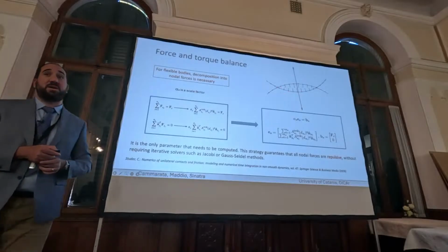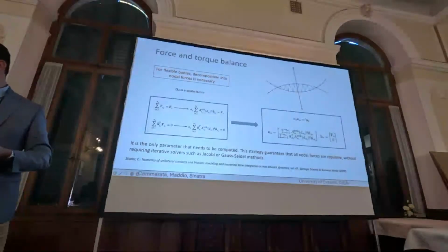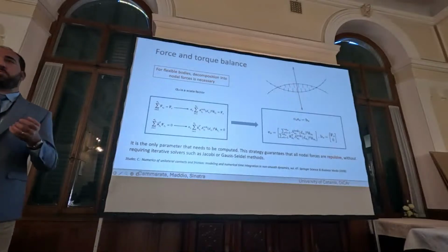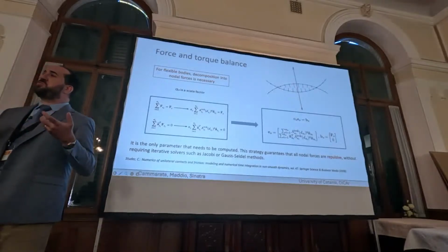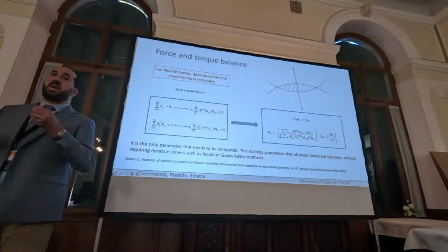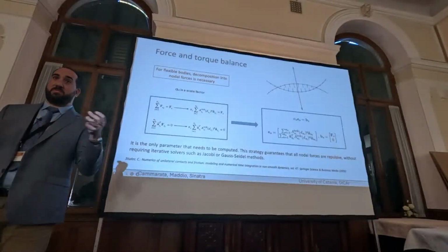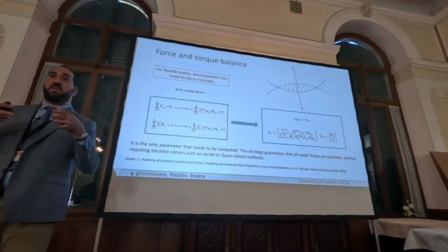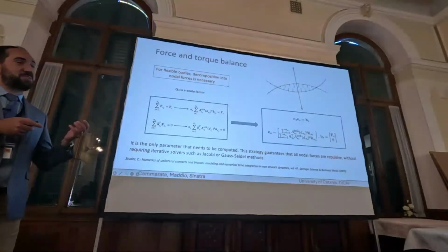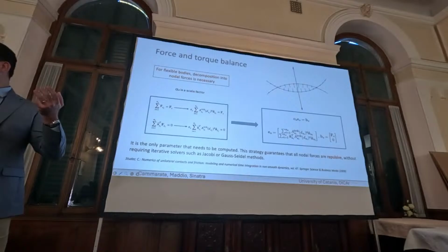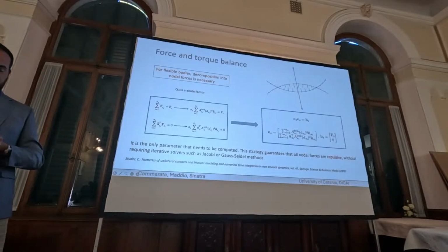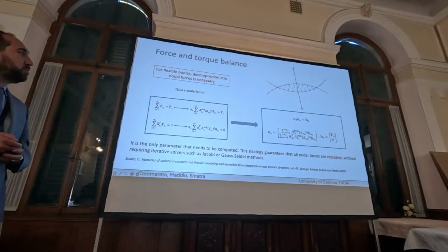But if we are interested in modeling flexible bodies, we have to perform an inverse process, because usually, for example, if you use the FEM, you start from the element, and then you assemble each element, which gives a contribution to the global force. In this case, we started from the global force. So we want to decompose the global force into the nodal contributions. So it's an opposite point of view.